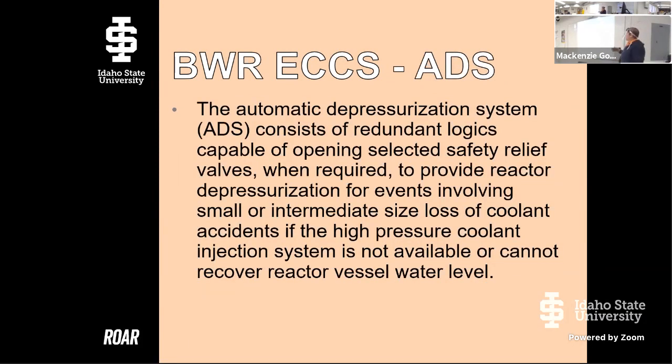The automatic depressurization system, essentially, if it receives a signal, it opens a bunch of valve actuators, okay, that will open those valves. It provides depressurization for events with small or intermediate LOCAs, if, for some reason, our high pressure coolant injection system is not available.